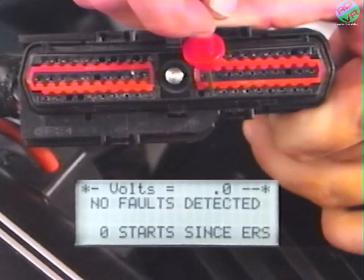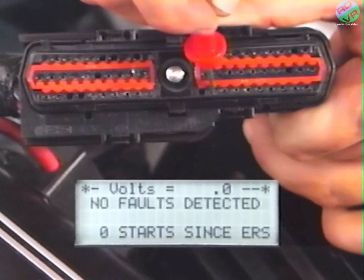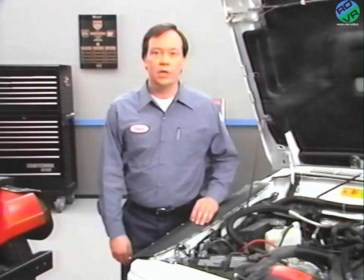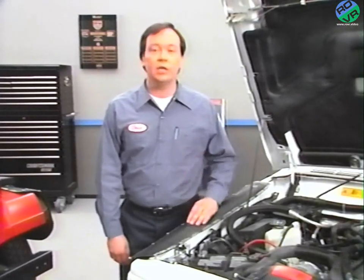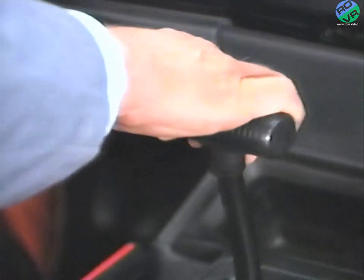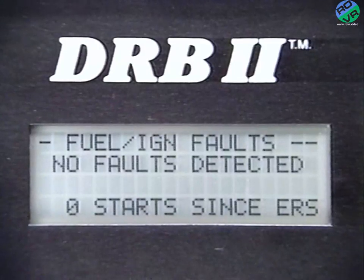If you obtained a reading below 10 volts when probing cavity number 9, you'll need to repair an open in the dark blue wire. If you got more than 10 volts, the engine controller is faulty and should be replaced. If the vehicle did not stall when you turned on the air conditioning, in an automatic equipped vehicle, you should hold the vehicle with the foot brake with the engine running and shift the transmission through all gears before returning it to park, and then use the DRBII to read fault messages.